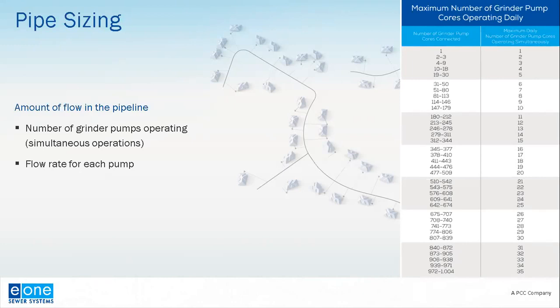The probability method is based on empirical evidence and data over the course of 50+ years of designing, installing and monitoring pressure sewer systems. It really goes back to 1969 with what's called the Albany study, where a number of grinder pumps were installed. And the theory was that only a certain amount would turn on at any given time, almost regardless of the circumstances. So the whole concept and objective behind the Albany study was to validate this theory of the probability method. But basically what it means is that at any given time, when it's sequenced out over a range of connections or pumps, only a certain amount of pumps can be expected to run at any given time, including during peak flow hours.